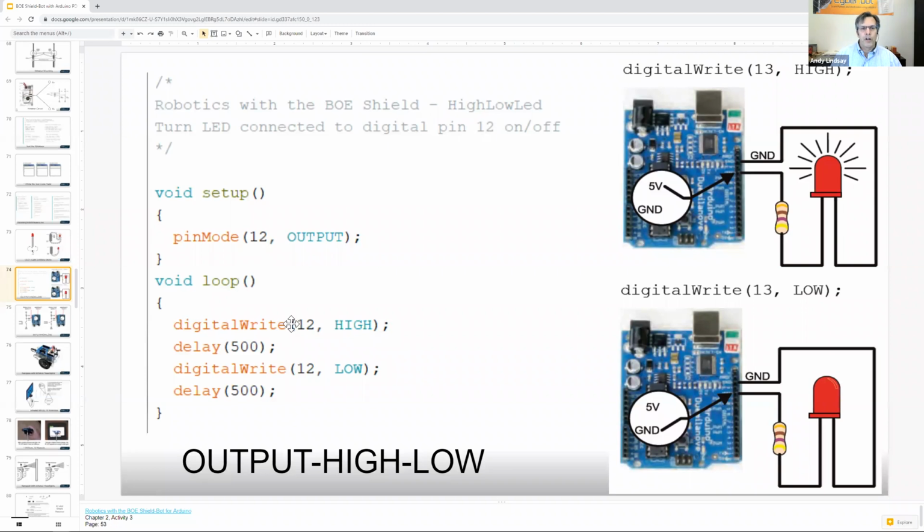And they'll know that digitalWrite 12 HIGH will make an LED connected to pin 12 turn on, and that digitalWrite 12 LOW will make it turn off. Well, one of the things that the book explains is that in order to do that, the microcontroller itself essentially connects the pin 12 to its 5-volt supply through transistors inside the chip.